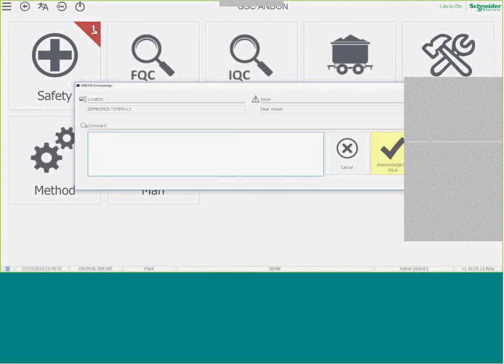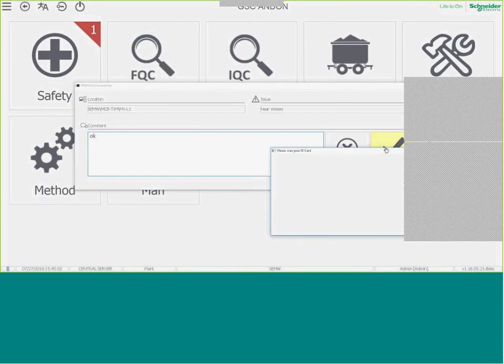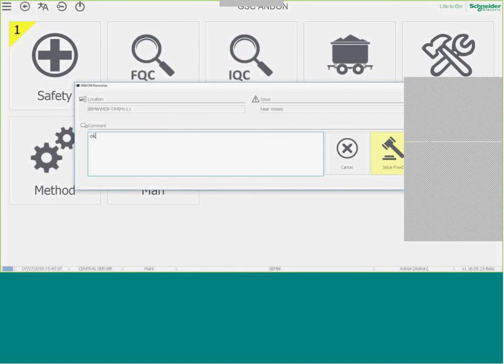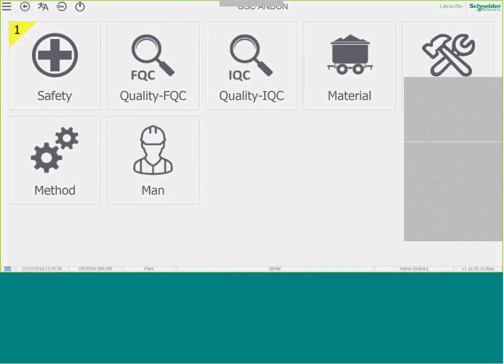Every time that PLC bit goes to 0, it means it was acknowledged or that it was fixed as well. So everything that is ready to use in the Andon template from a manual way can be very easily triggered automatically by bits in the PLC or robot or any other external system.